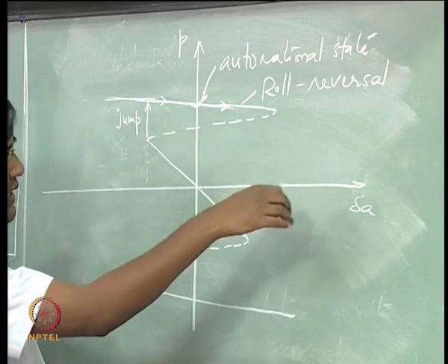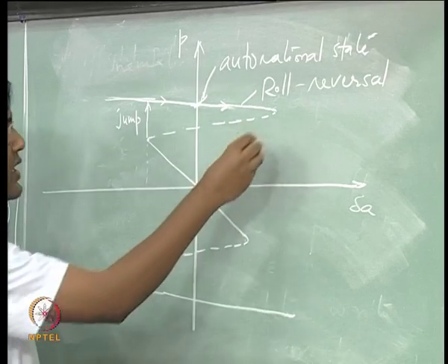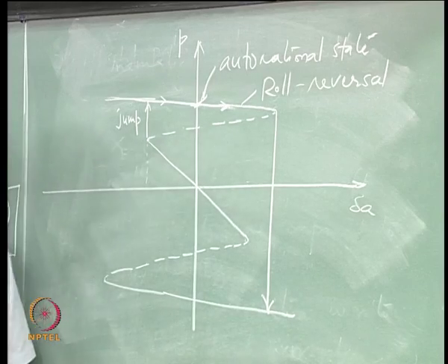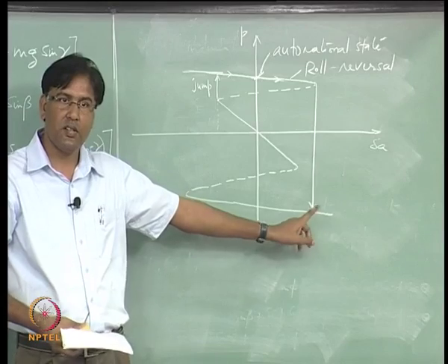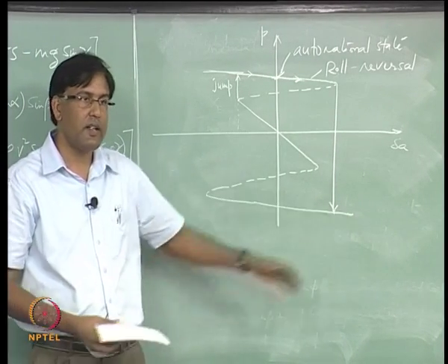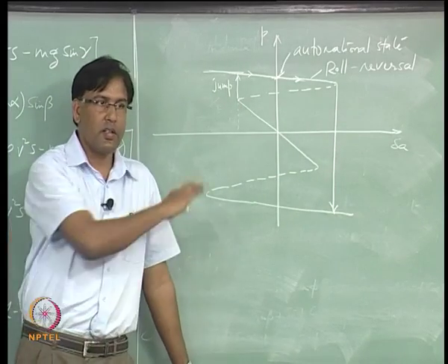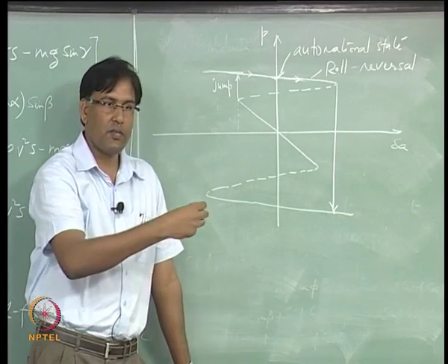So, you decrease the aileron further in the opposite direction and you see that you have a larger jump in roll rate, and now you are landing yourself into this solution branch, right, because this is what is available to you. All the solutions are here, okay, where you can go by applying your aileron.